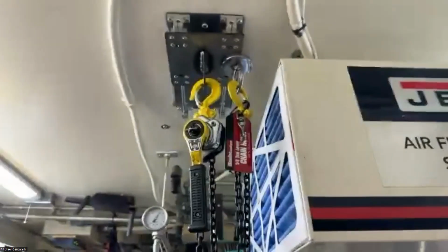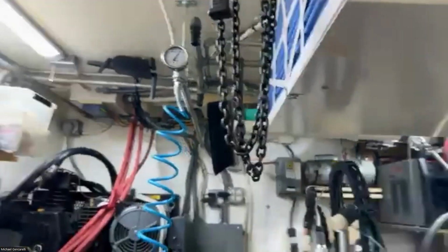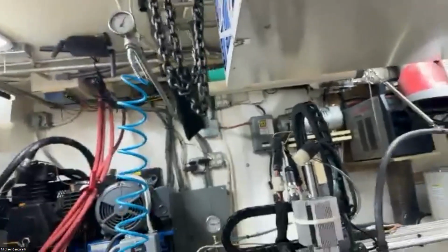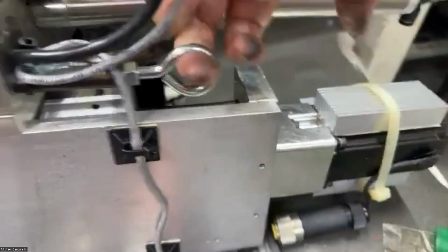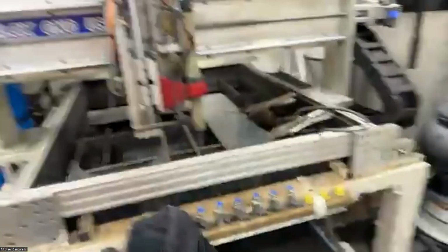You take out the 4 screws. I've got a hoist up there again because I've got a bad back. I bring the table all the way out and hook the hoist up to it. I've got a ring on both of them that I can just grab, take out 4 screws, pull the head off, put it down, put the next head on, plug everything back in and start going. From routing to plasma in probably 35 minutes, maybe.